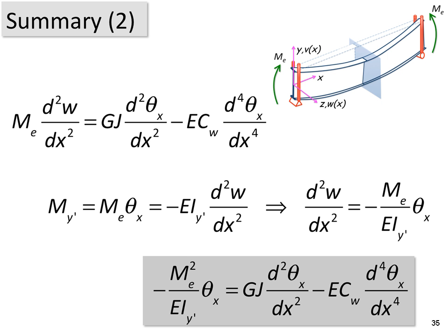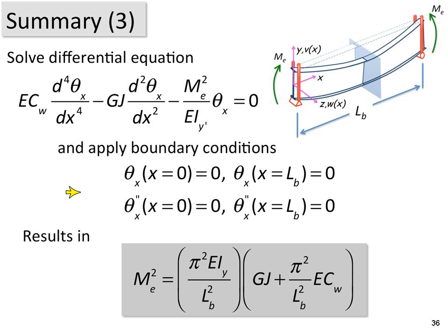So I showed in the first lecture that you could go now to some type of program. Again, our students today don't roll up their sleeves and actually solve the differential equations by hand. They use some type of symbolic processor. I think I showed you the Wolfram solver last week. You could fire it up again and use this one. And if you actually solve this differential equation and then apply some boundary conditions, you'll get a solution for the elastic buckling moment.